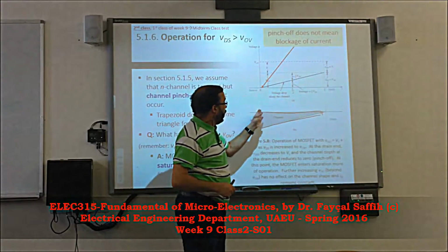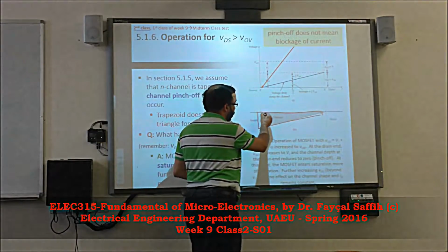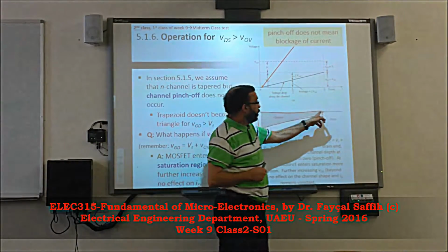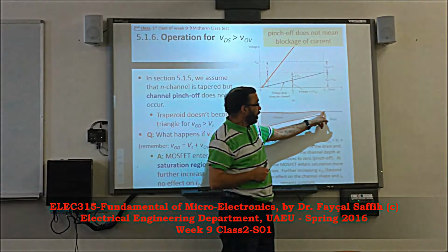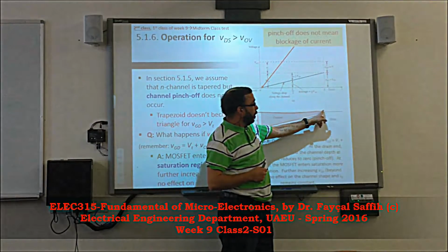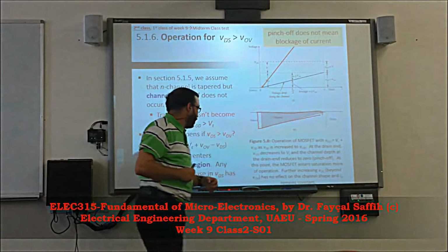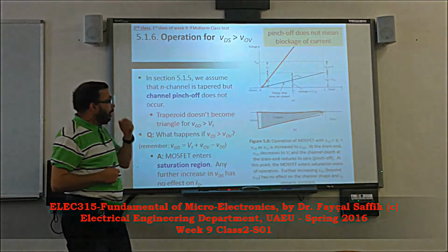So the total voltage here is actually the total overdrive, but here the voltage of the channel is not the overdrive, it's the overdrive minus VDS.